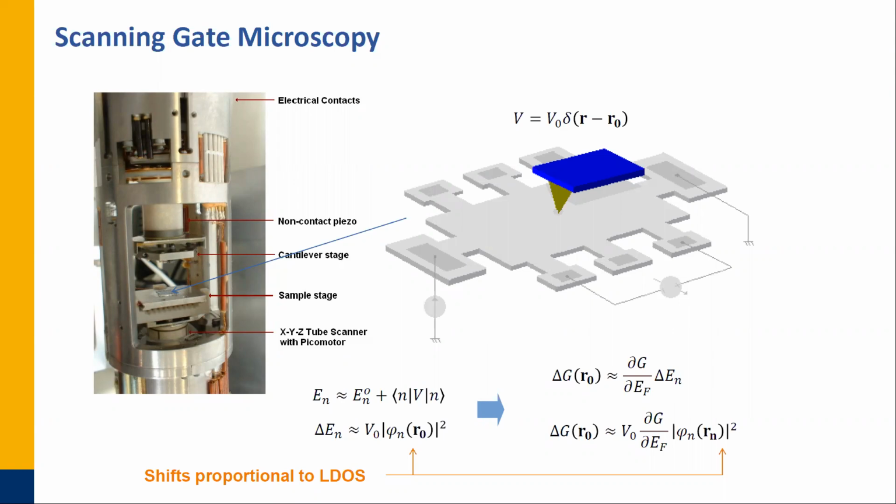We have to modify the tip because usually you use light and an optical detector with quadrants, but we cannot afford to have light in our electrical system because it generates heat. So we have to use a piezoelectric tip, which we could only find in Japan. We also have to modify the electronics of the system to accommodate this electrical piezoelectric tip. Any other question?